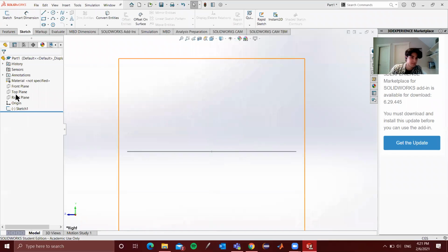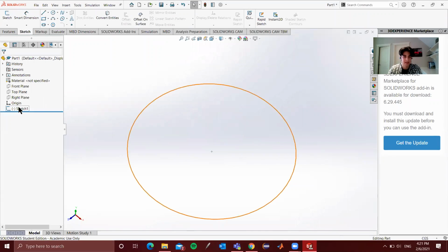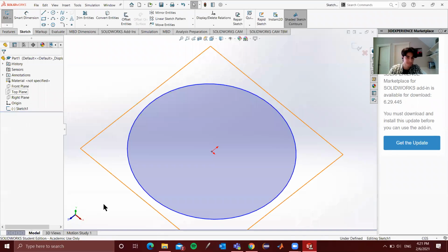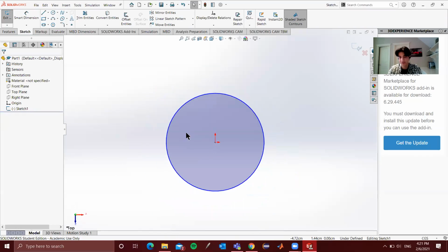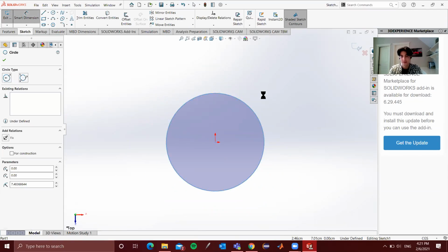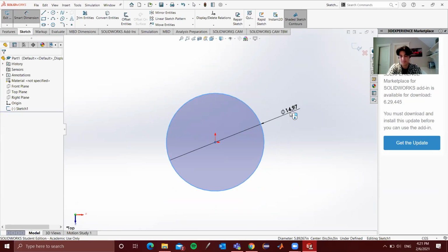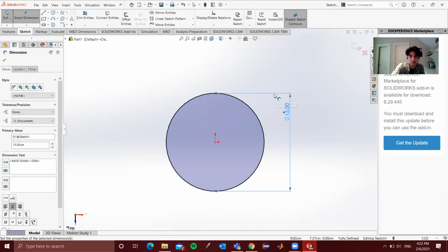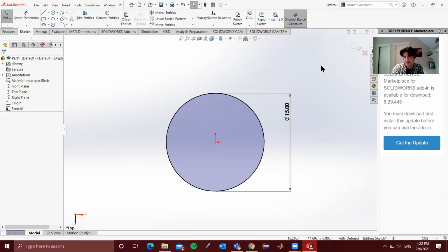Yeah, okay, perfect. So I'm going to go back to editing this sketch by right-clicking on the sketch and pressing Edit Sketch. And you'll notice it's underdefined as well, as per usual. So what I'm going to do is add a dimension to it. And you'll notice this circle with one dimension is fully defined. And you may ask, why is that the case? Why did we have to constrain multiple things with the rectangle in the previous dimension?